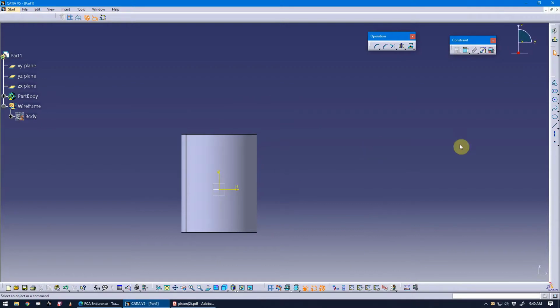I'm in my sketching environment, and then I'm going to change to construction, and I'm going to go under the operations toolbar, and under project 3D elements I'm going to select project 3D canonical silhouette edges, and that's going to project the limiting elements onto my sketch plane as construction geometry, since I have construction geometry selected.